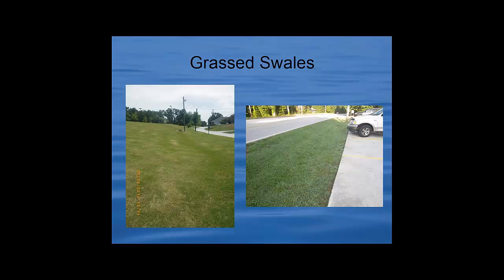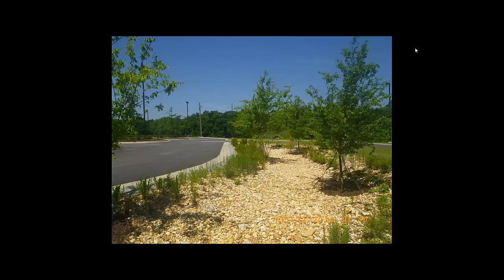We also constructed a new courthouse. Clarksville is the county seat. We constructed a new courthouse, which has been the biggest construction project in the city limits in the past decade. Again, note the absence of curb and gutter, sheet flow from the parking lot. In stormwater management, concentrated flow can be your enemy. If you can spread it out, you stand a better chance to allow it to soak in.